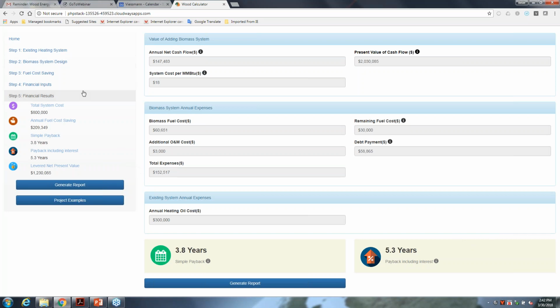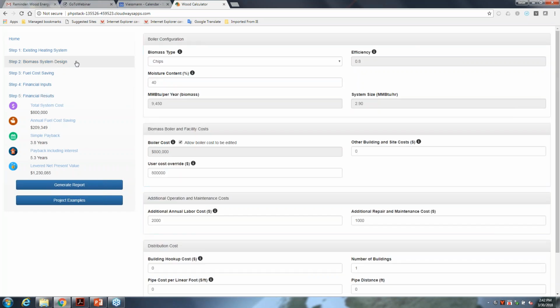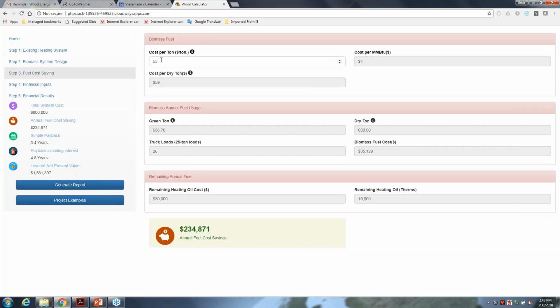So now that I'm here, let's talk about some what-if games that we might be able to play. Let's go back and say this system was chips, right? But we know that chip system is probably more expensive because we could store pellets in a silo and have them deliver gravity. So why don't I change that to pellets? It's going to default to moisture content of 6%, which is about right for the US. And now when I go to fuel cost savings, I'm not going to buy pellets at $55 a ton, bulk delivery. I might have to pay $220 to get those delivered. You can see the cost per dry ton is not very different because they're very dry to begin with.